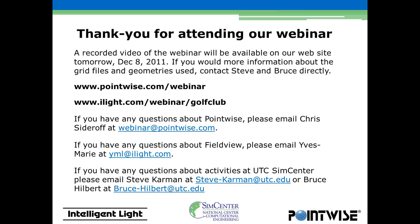Again, I think this is another question for maybe Steve and Bruce from Harris Hamid. How do you go about selecting the size of the structured block for capturing the wake? Experience, basically. I will put as many hex cells behind an object as I think I can get away with in terms of point count. I probably could have done a lot more in this case because we only had a 2 million point grid, which we have the capability to handle, but I just said, this is about right. Plus, once you have a solution in hand, you can actually post-process it and figure out whether you captured it adequately or not, and then go back and do a remesh and do it again.